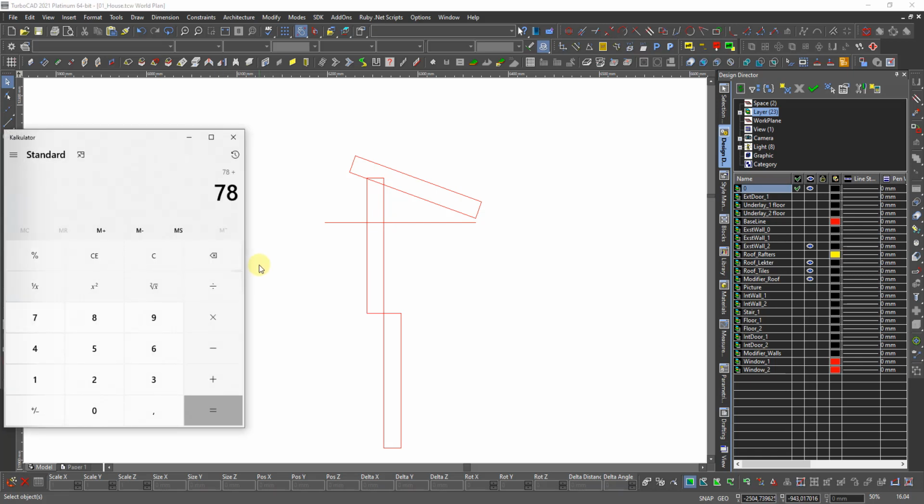And then we know we have 78 plus 40 is 118, and I like to have like 20-25 millimeter overlap. So then I say use 32. It'd be 119, 120... 140.